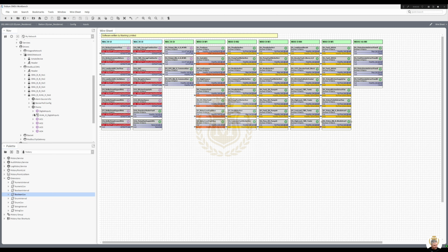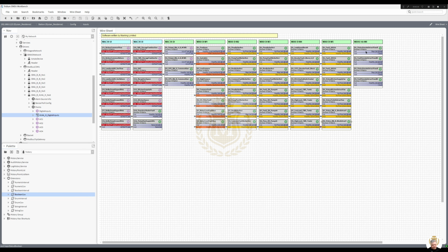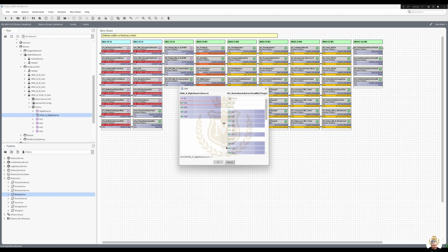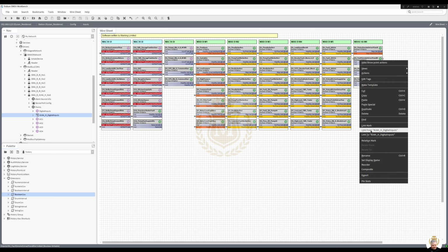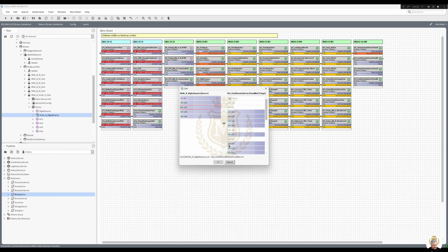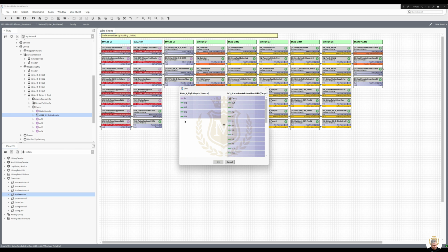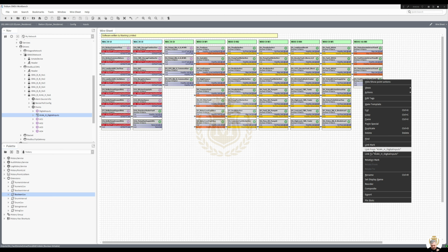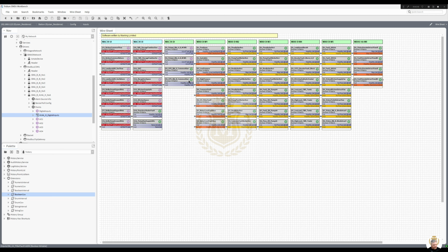Just finally this one. Link mark, all digital inputs, so we don't need to use individual ones. We can just go into here, link from UI2 into there, link from UI3 into there, link from UI4 into there. So now we've completed all our I/O.